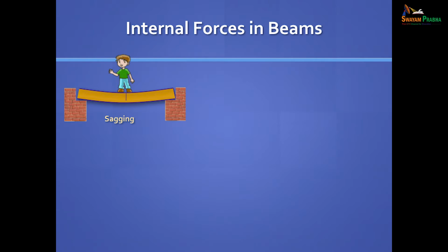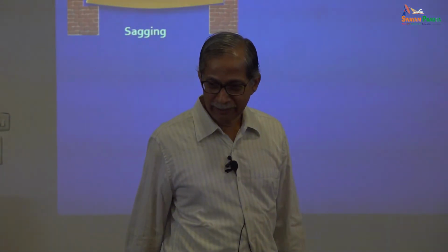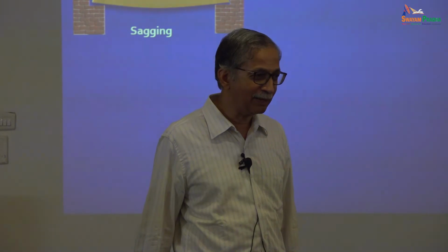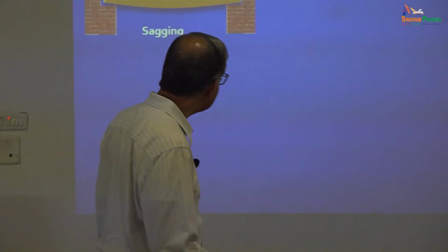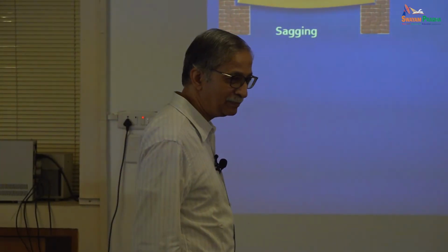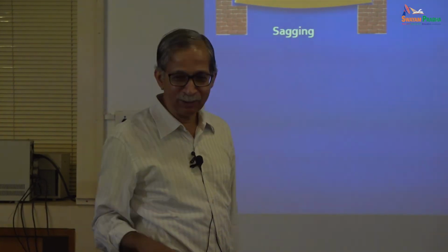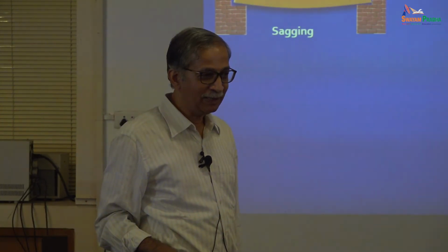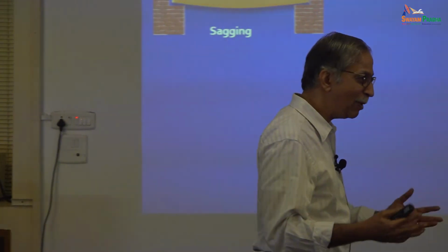So this is sagging. Very nice, simple picture. Now, if you look carefully, can you draw the bending moment diagram for this guy, for this loading? He's standing with 2 feet, right? So what kind of bending moment diagram do you expect? Is this pure bending? You draw one curve like that, it looks clean, pure bending. It's not. In pure bending, what is pure bending? We gave you 2 examples. One, kinematically induced, the other, statically induced.